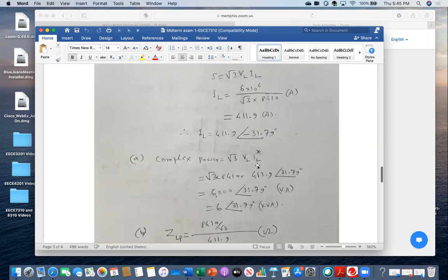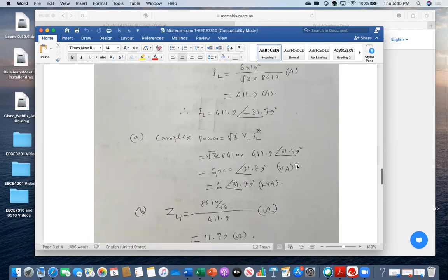And then here in complex power, because I will conjugate, you see I have changed the sign. This is plus, and this is volt ampere. Here I have expressed it in kVA, 6 angle this one. Now you see here I just put it in polar format. You might express it in rectangular format, like this, P plus jQ. In that format, it is the same. Okay.